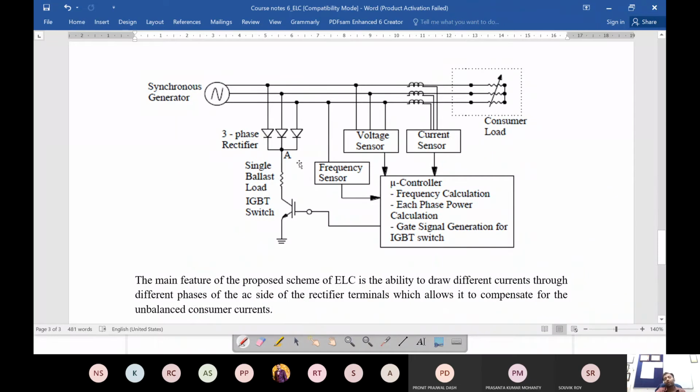And yeah, that power loss will always be there. That is the concept only, that you don't change the generation, you change the load. So some power by definition you are going to waste. But the only good advantage can be that if you can find a utilization or a useful application for that dummy load, then the entire system efficiency would be better.